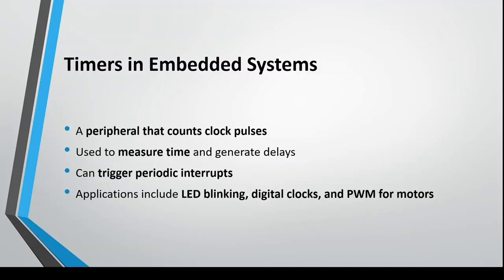Timers in embedded systems. Timers are peripherals that count clock pulses to measure time. They are used to create delays, generate periodic interrupts, and perform time-based operations. In my microwave oven project, timers are used to implement the cooking countdown.